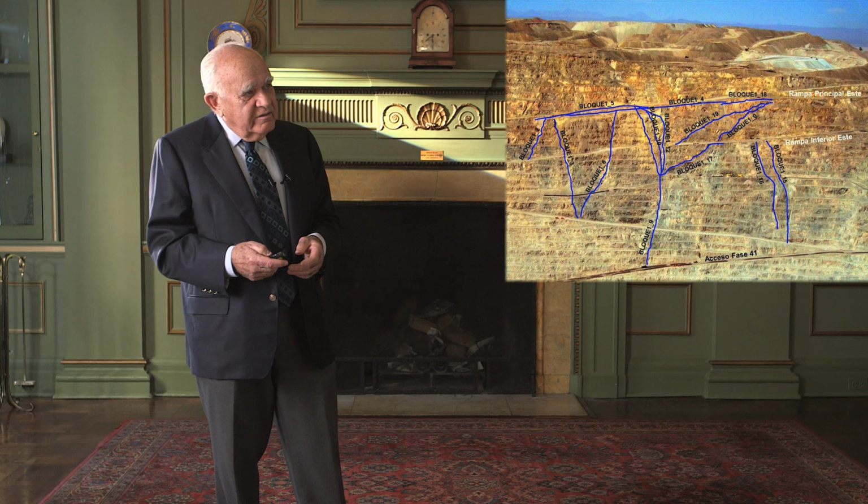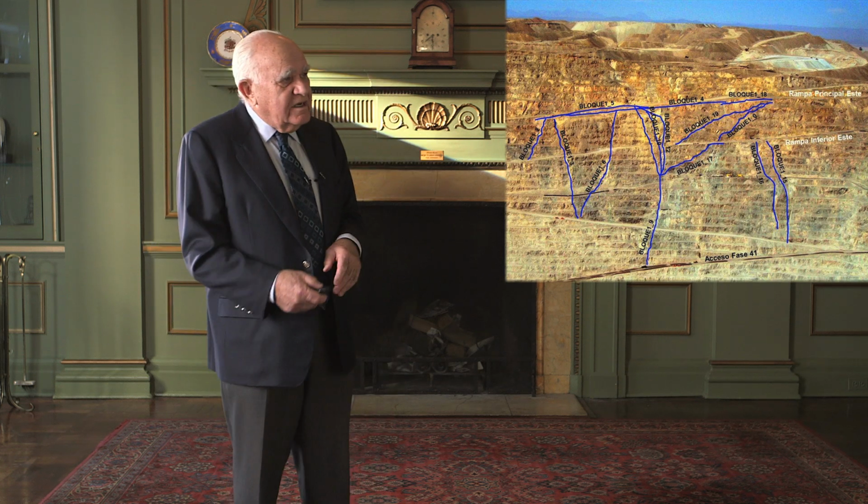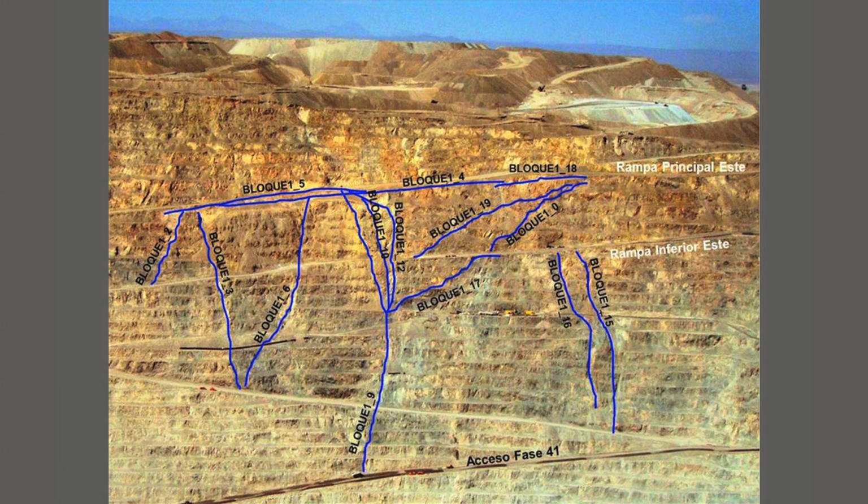And one of the examples I'd like to quote in this lecture to illustrate how it's dealt with today is this one here, which concerns the stability of this block of rock here. That slope that you're looking at there is about 300 meters, the top 300 meters of the 1,000-meter pit, and the concern is how stable is that block. The process that is used here is to map the structures from either mapping along the benches or from core,